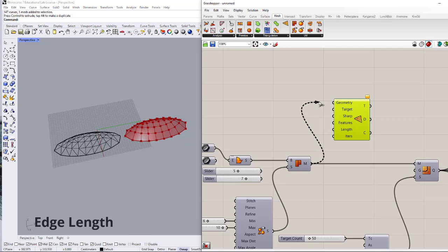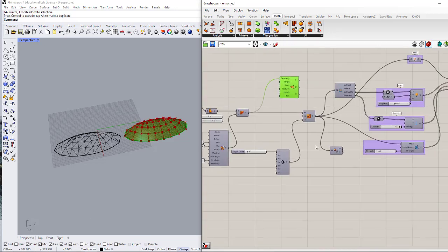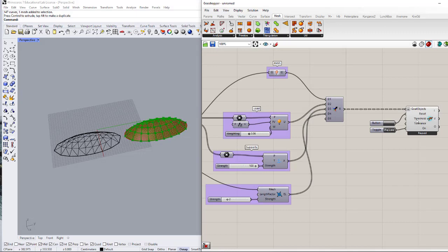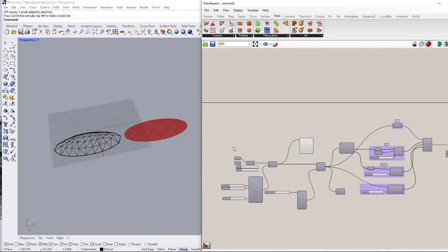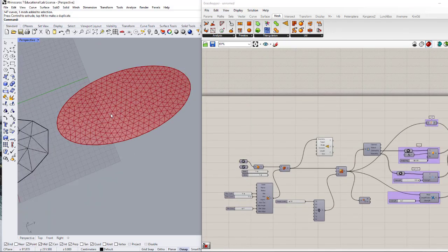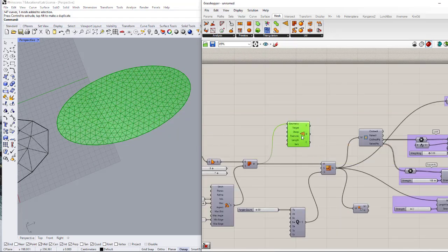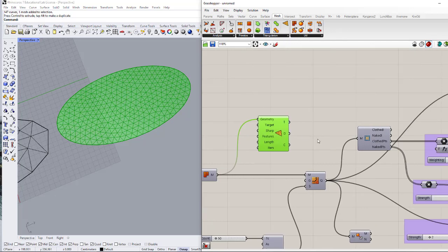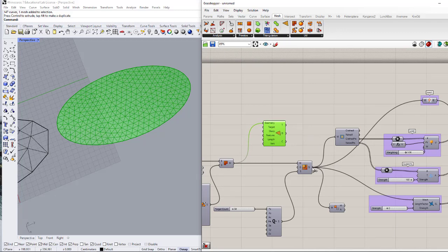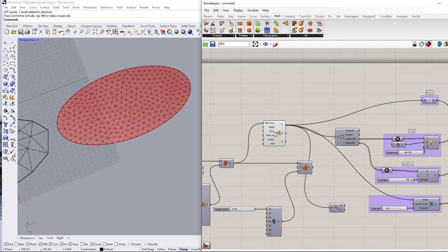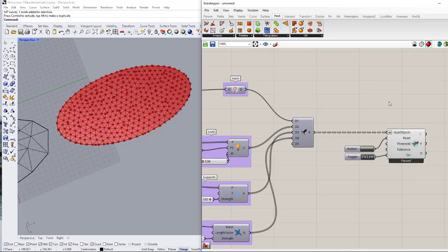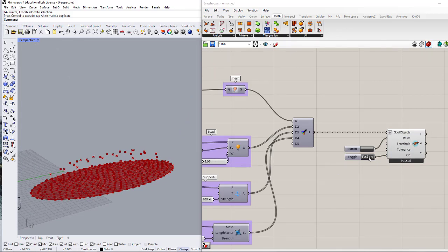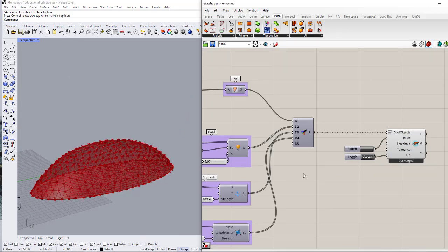And if I connect this geometry, and let's false this component and hide it, you can see that it's now different. It's more like an equilateral triangular mesh, and this is the output, the remesh result. And now let's connect everything to this output and unhide our result and make it true.